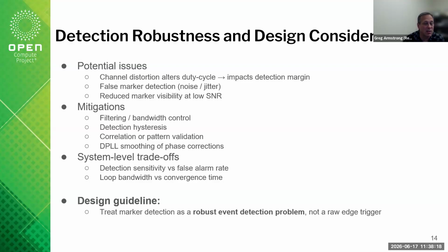Repeating the same time in 2 cycles would be very bad for PTP because then it looks like they happened at the same time when they really didn't, right? Physically, they did not happen at the same time. So you don't want to create that condition just because of your mitigation techniques of handling a movement of where you think that 1 pulse per second is really in your system.